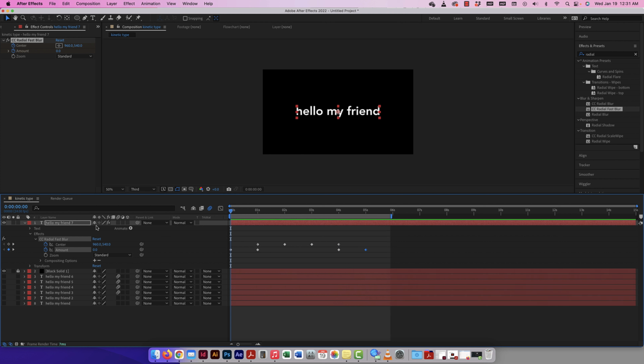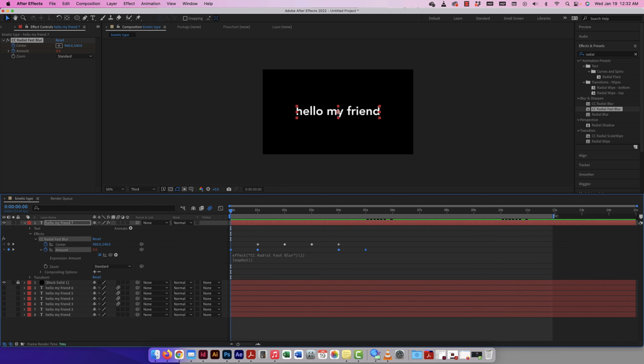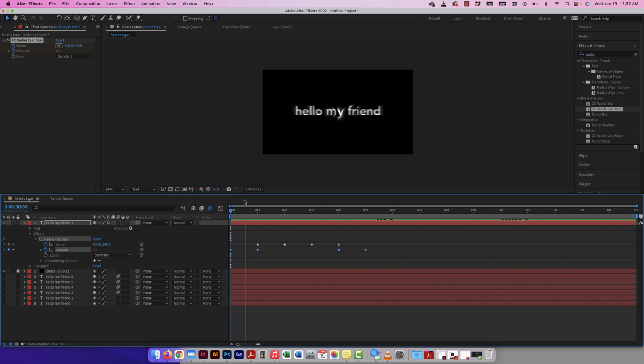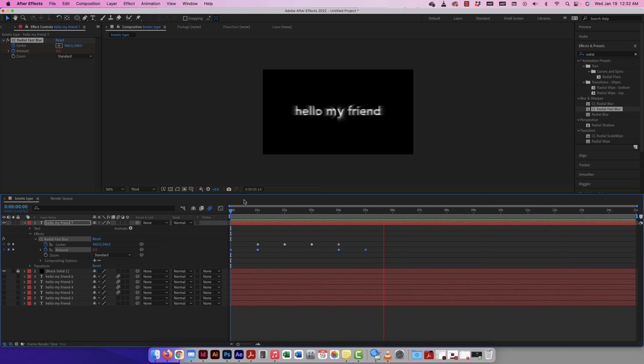If I wanted to, I could animate this and actually loop it. So let's see what looping does here. I'm going to hold down Option and click on my stopwatch, and I'm going to loop out. I'm just going to press enter from here, because this is already an expression we need. I'm just going to type in the word loop, and I want to loop out. So I double click on that, and let's see what happens. I'm going to bring this all the way so I see the full animation. Let's see what actually loops here. And let's see if this animation constantly loops.